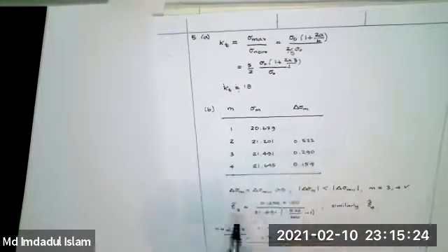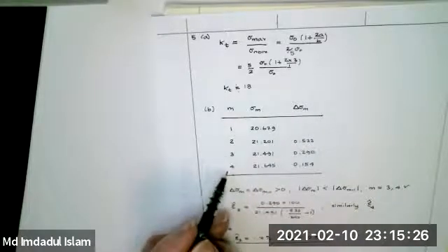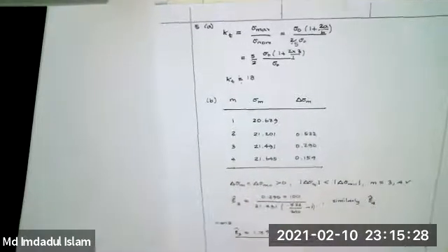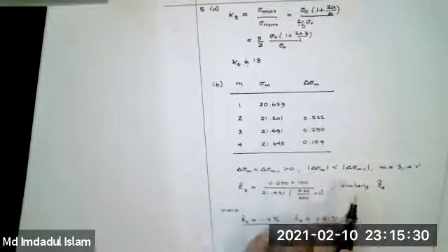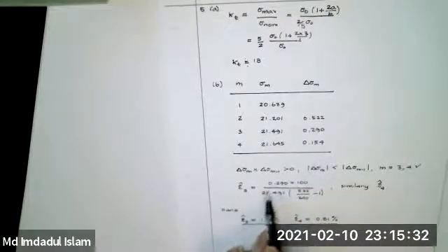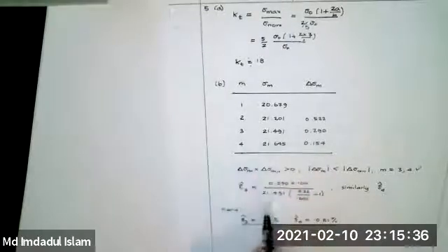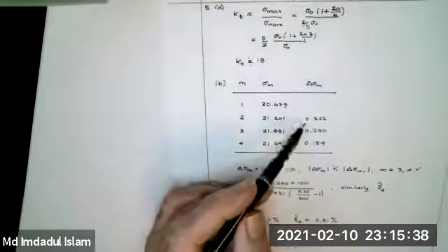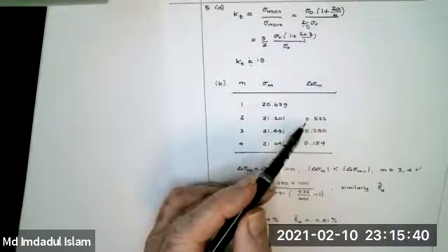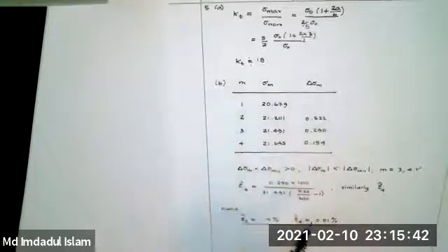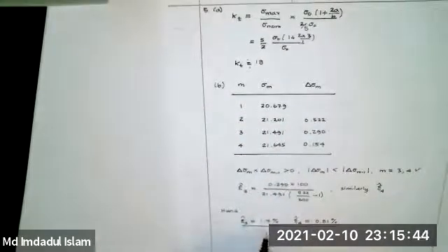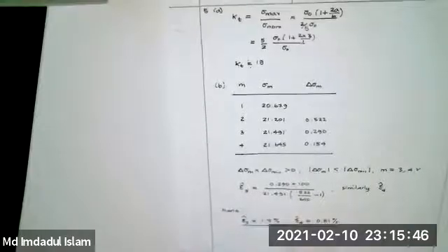So they check. Sometimes it'll just be for m equals 3, and sometimes it might be just for m equals 4. I'll explain that in a little bit. Then once you've got these convergence requirements, you go calculate the error. It's 0.29 times 100 divided by its value, 21.491, times delta sigma m minus 1, 0.522 over 0.29 minus 1. And when you calculate that, you get 1.7%.